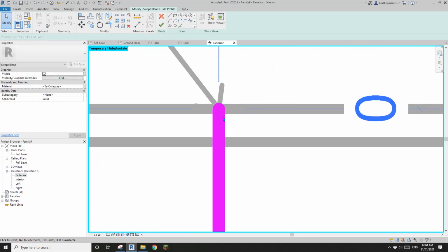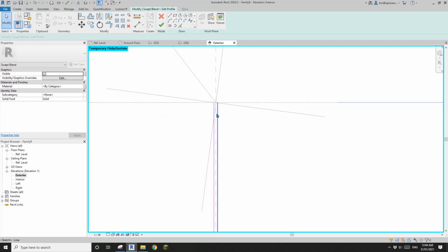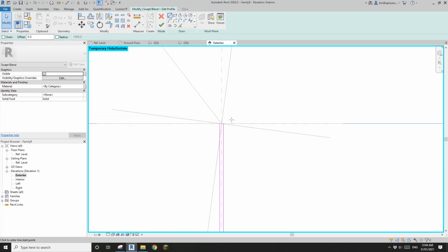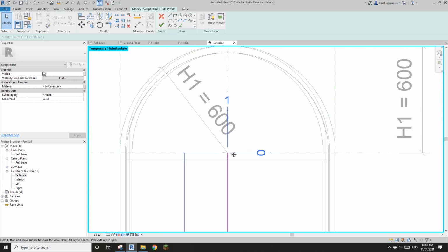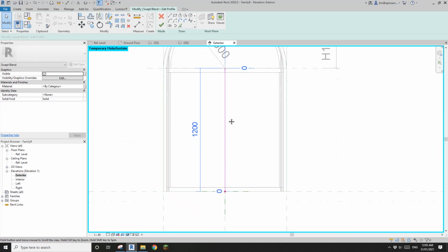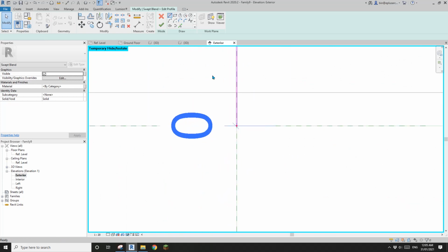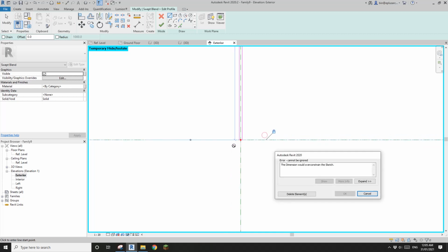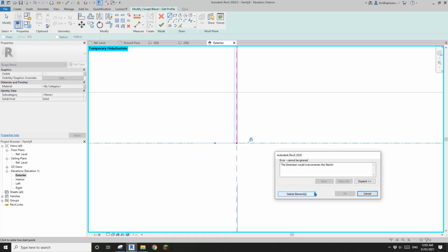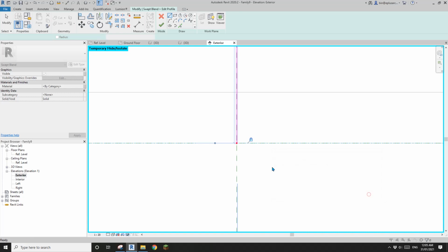And then if I zoom in, TL, so change to thin line, and then I'll connect, oh no, not connect them. I'm going to need to create an arch, okay? And I'll just connect this end, so connect this, and also I want to lock them, oops, wrong one, with over constraint, or maybe cancel it.